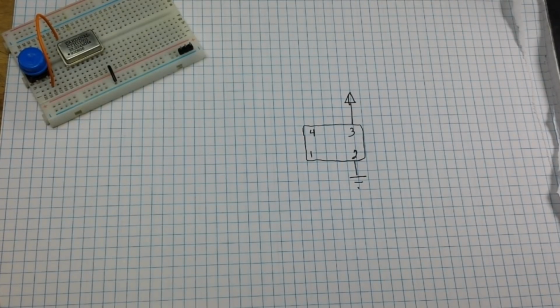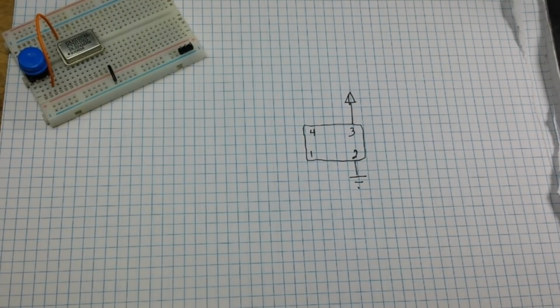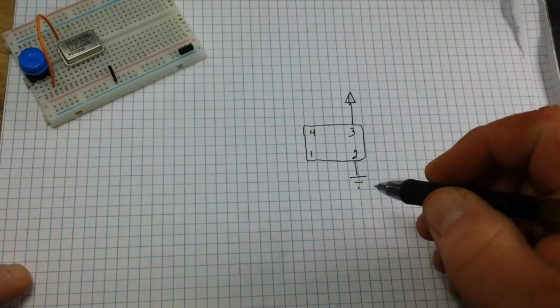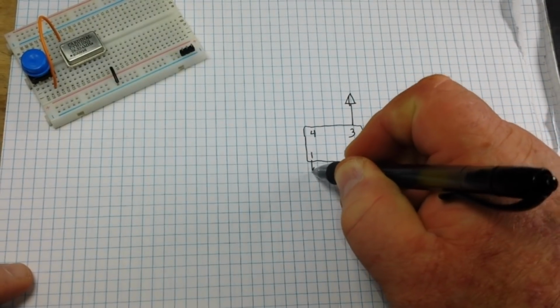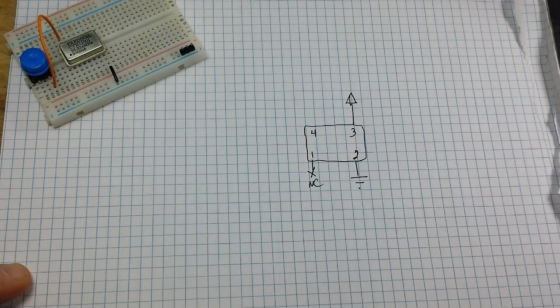Now, you always want to have a resonant antenna. Doesn't matter so much for receiving, but it matters very much for transmitting. If your antenna isn't resonant, some of the power that we put into the circuit is going to bounce back, and that's going to create standing waves. And standing waves are bad. Not only do they rob you of power, but they can damage a high-powered transmitter, and yeah, it's just not good. Okay. Now remember, pin 1 is not connected.